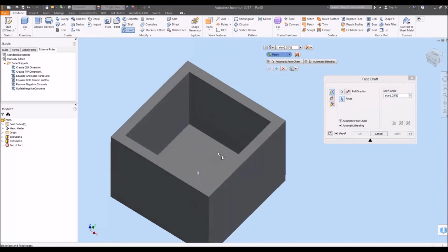And now it's going to ask for any of the walls that we want to do the tapering. So what we're going to basically do is go around either counterclockwise or clockwise. And our selection, this is where it becomes important, where you select on this actual square. So even though we want to actually select this wall, it's important to note that if we select the top of it up here, it's going to want to use this edge as the rotation point, or it's hinged. So if we select down here,